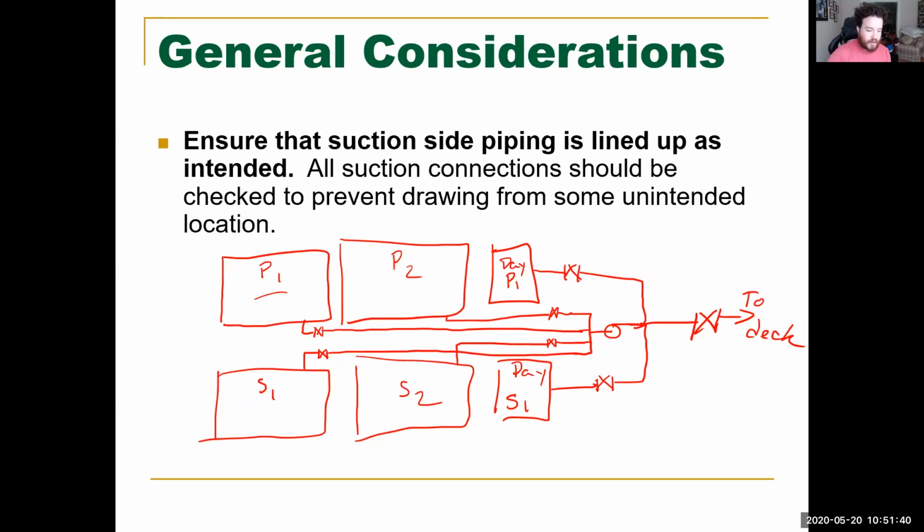All right. Even if you're messing around with bilge water or potable water, and especially potable water, where it really doesn't matter, unless you're pumping into one of your own bilges and you start flooding out a bilge. But it's one of those things, get in the habit now of double checking your lineup. And the best way to do it is to put your hand physically on it. That's the way I was taught.